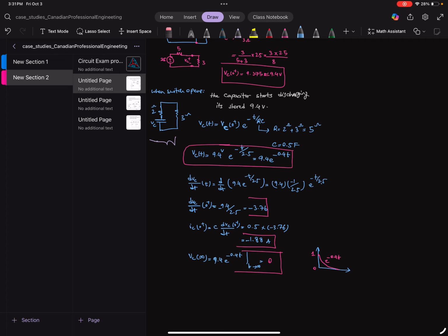That's why sometimes when you turn off a circuit, they say, before you turn it on, wait a couple of seconds for the capacitors to discharge completely, and then you turn it back on and they start working properly. Also, sometimes you have to short circuit some of the capacitors to fully discharge them. Otherwise, they are going to hold some voltage across them, right? Or you have to be careful not to shock yourself with the capacitors, because they will discharge across your body, basically.